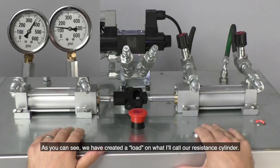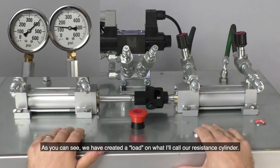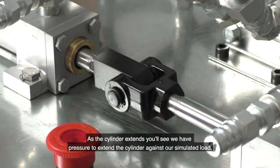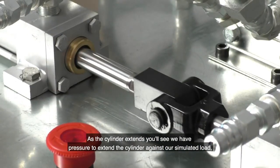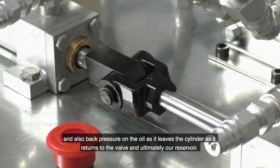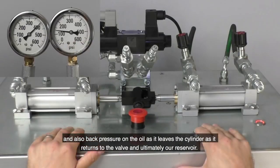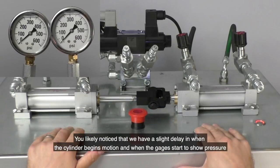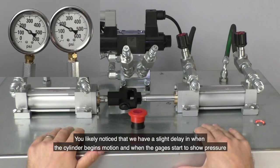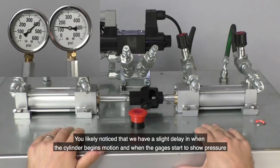Now, let's run through the exercise and capture some information using the test circuit shown here. As you can see, we have created a load on what I'll call our resistance cylinder. As the cylinder extends, you'll see we have pressure to extend the cylinder against our simulated load and also back pressure as the oil leaves the cylinder and returns ultimately to our reservoir. You likely have noticed that we have a slight delay when the cylinder begins motion and when the gauge starts to show pressure.